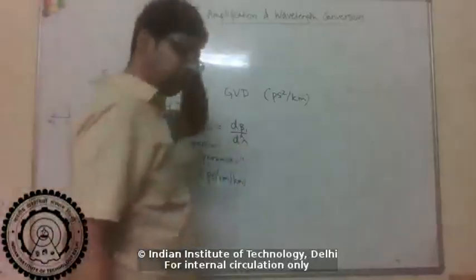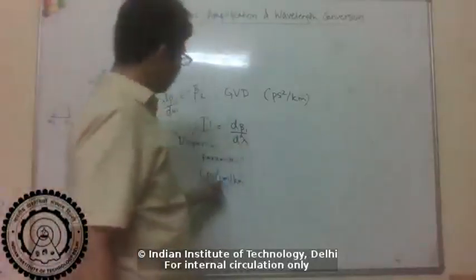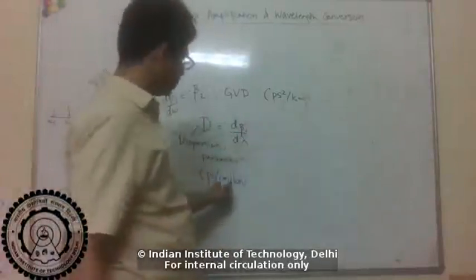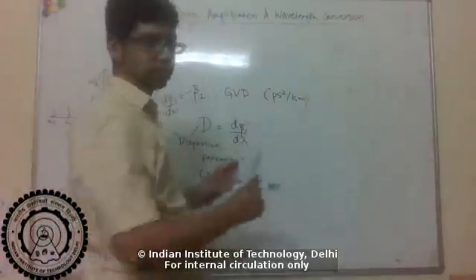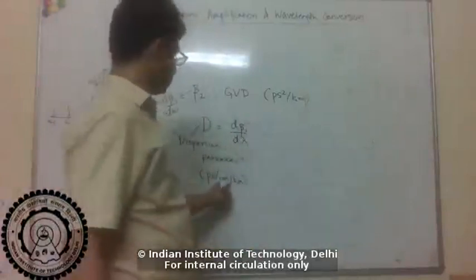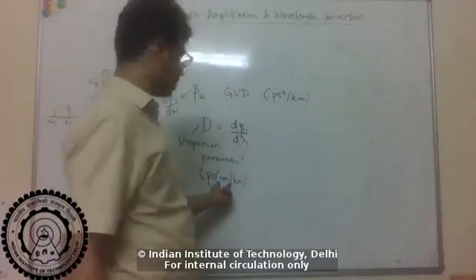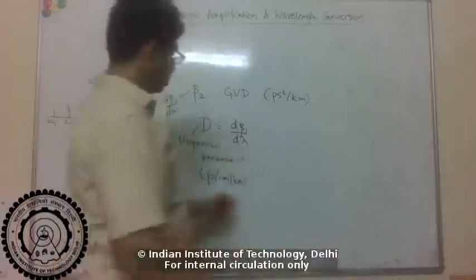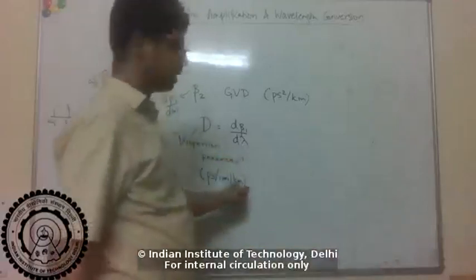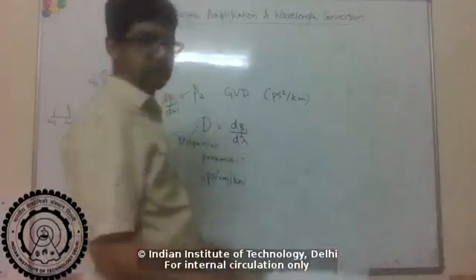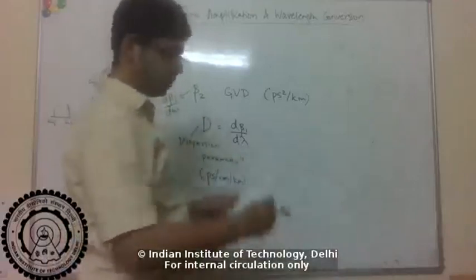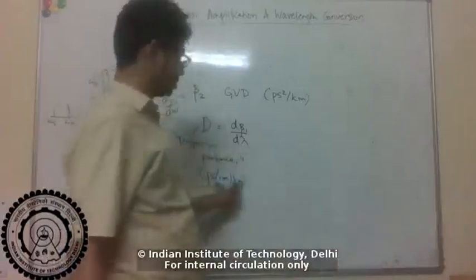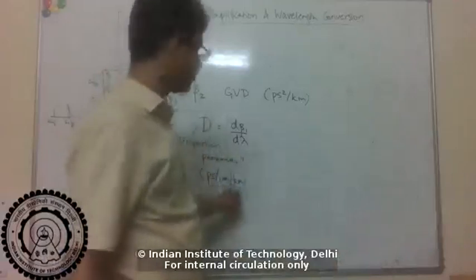Okay, again, this is coming from optical communications, which says that if I have some optical pulse of certain bandwidth, which is measured in nanometers, so it has some spread of wavelengths of some nanometers, and then it travels through some fiber of certain kilometers length, then the spreading that the pulse will get will be D picoseconds times the bandwidth in nanometer times the length in kilometer.